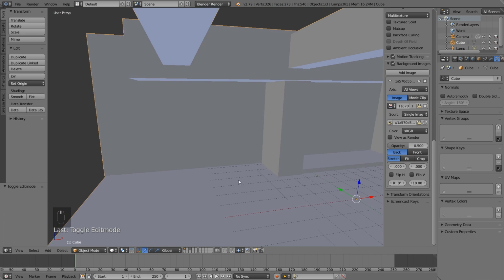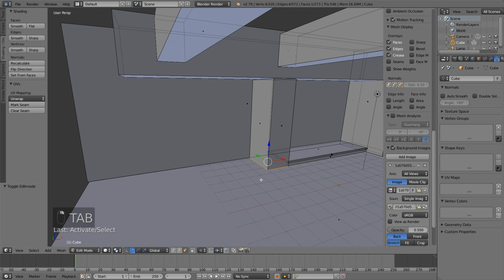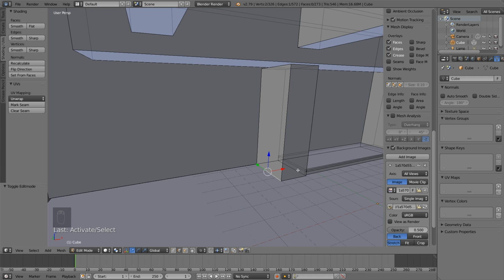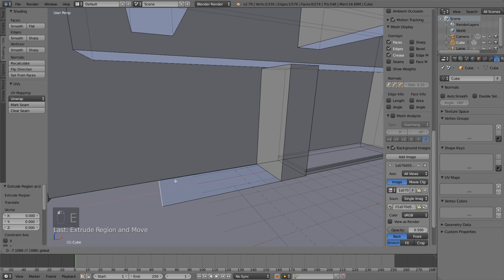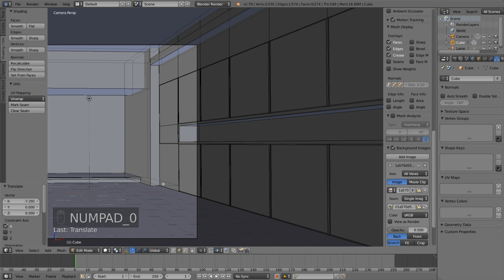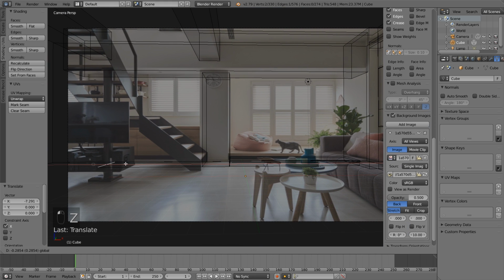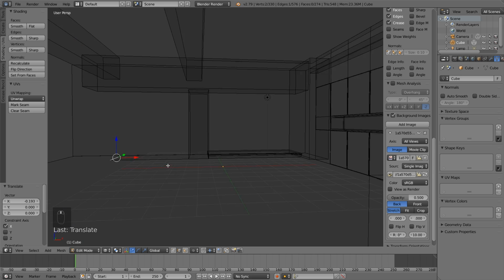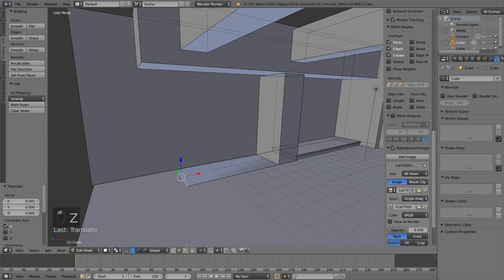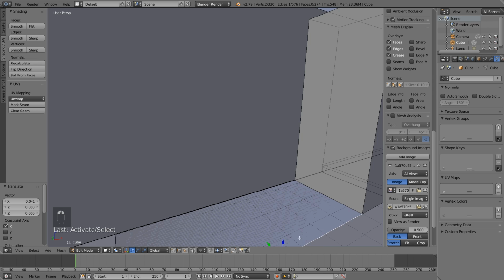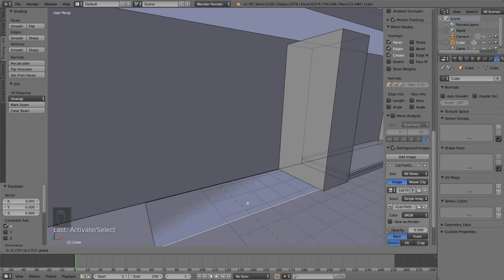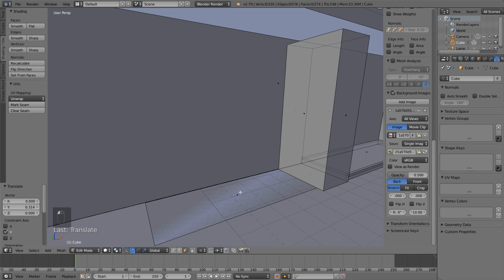So the cabinets are pretty basic as well, and we can pretty much use the same sort of technique we just used on the floor there for that little raised floor, except we're going to do a little bit of a change. So I'm going to go ahead and Shift D this. Let me Control Z, Shift D, yep, and then escape to not move it. Extrude it out about the approximate size of 3 cabinets. You could use the camera view here if you wanted to get more precise, but it's going to be right around there. All right, and then I'm going to extrude it up, but first I'm going to pull this back. So pull it back a bit. These are kind of set back a little bit further than the floor even, this floor here.